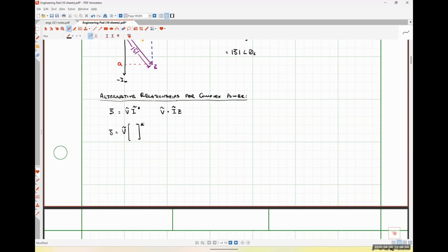So using that Ohm's law relationship and manipulating it, I can see pretty easily that I is just V divided by Z. So that would give me an RMS phasor voltage V in my numerator divided by Z in my denominator. Well, as it turns out, when I take the conjugate of a fraction, that's the same thing as conjugating the numerator and conjugating the denominator. So I could rewrite this as V conjugate times V, because the order of operations for multiplication doesn't matter.